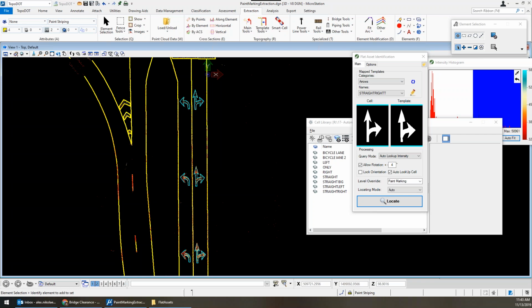Daniel Clark from California asked if the cross-slope analysis uses only the line work and not the point cloud, and that's correct. You would need to extract the line work in order to run the tool, and it would only use the line work to make the analysis, so it doesn't actually sample the data at all.